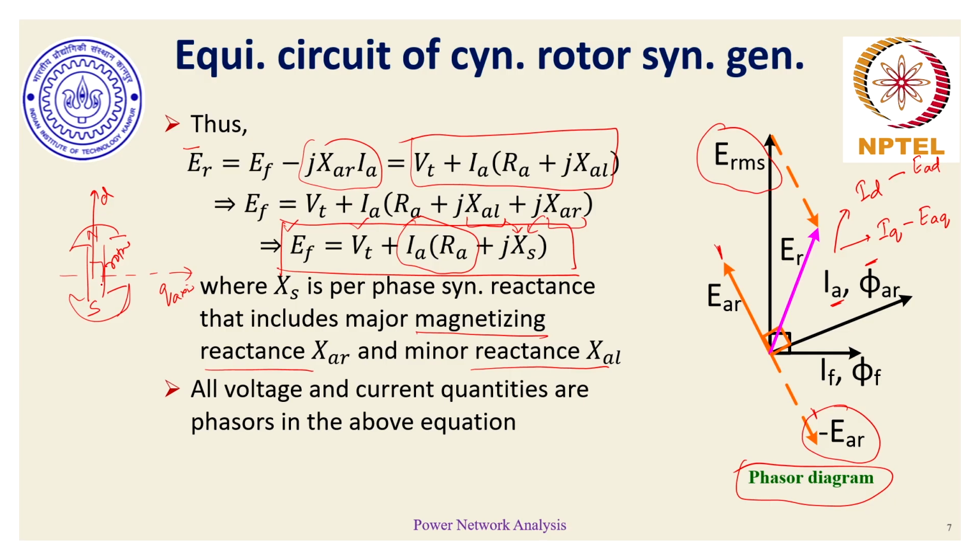So now if we look at the salient pole rotor, one can easily understand that the induced EMF, which is the result of the rotor current, is aligned along this direct axis. So let's say if we mark EF, which is also ERMS, at an angle delta, then the corresponding direct axis component reaction voltage would typically be in the opposite direction to the direct axis current.